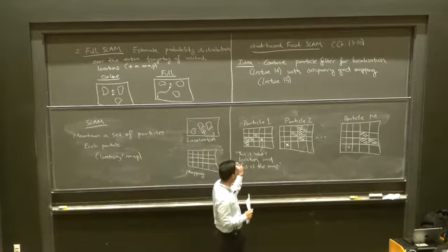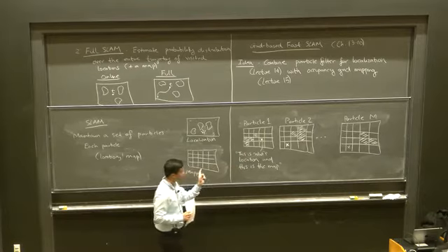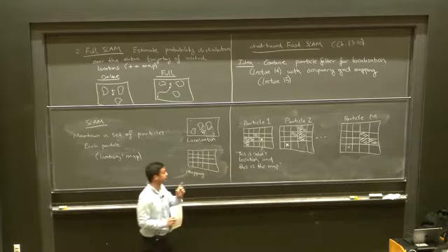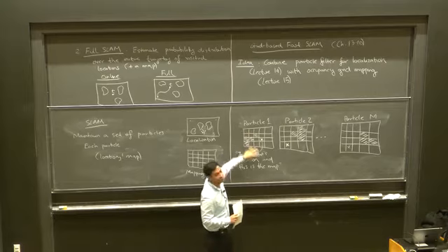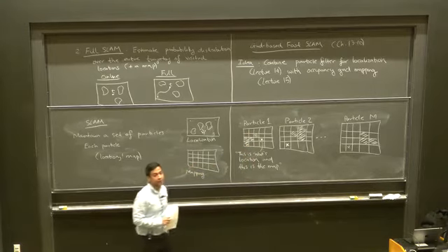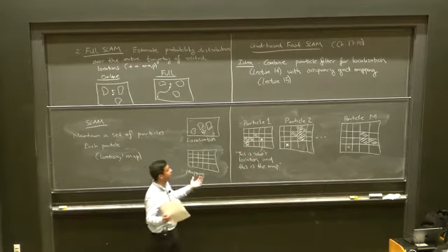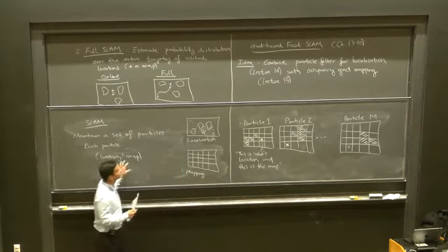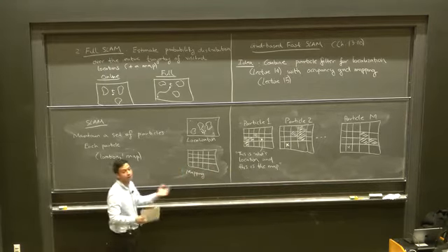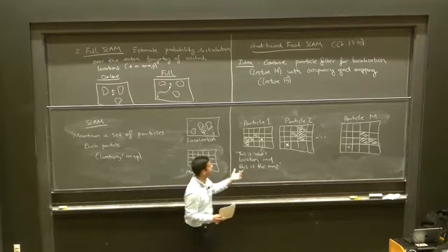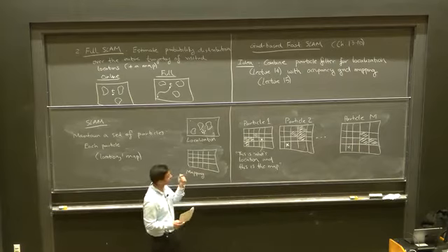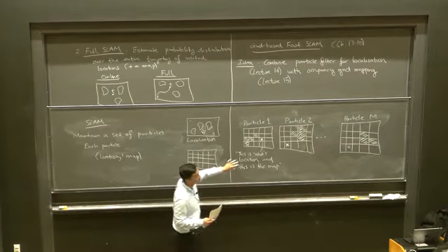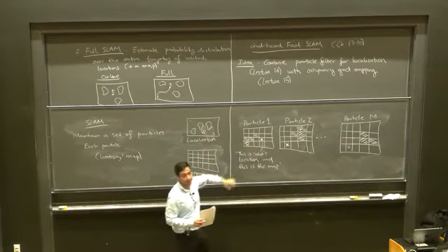It has dimension equal to the robot's location dimension plus however many cells you have in your grid. So it's a very high dimensional space that we're trying to represent a distribution over. But we're doing this approximately via particles, and each particle is one particular instantiation of a location and a map. Does that make sense?